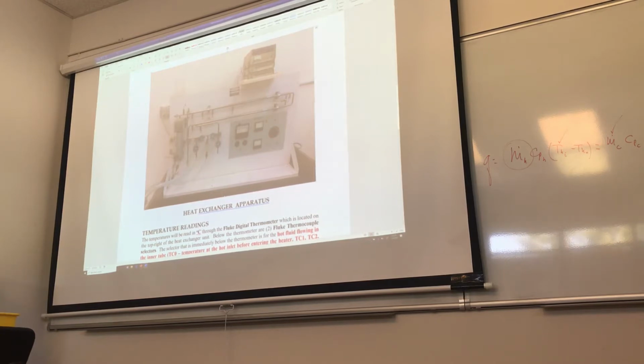to do the parallel flow heat exchanger, you see here, the fluid is moving from left to right, like that, right? To mimic the parallel flow heat exchanger, this is where the cold fluid comes in, through this. And then to simulate the parallel flow, what we do is we close this valve, right?